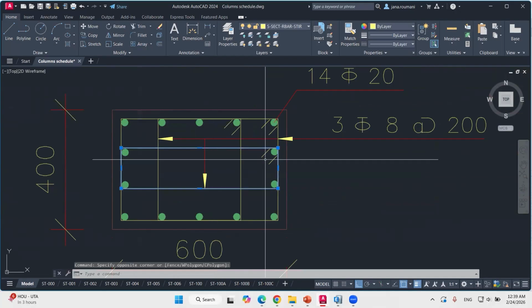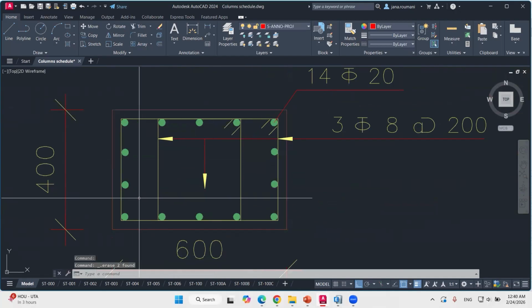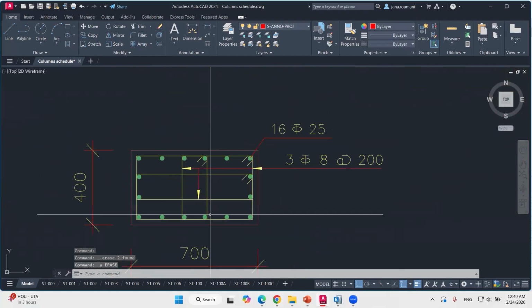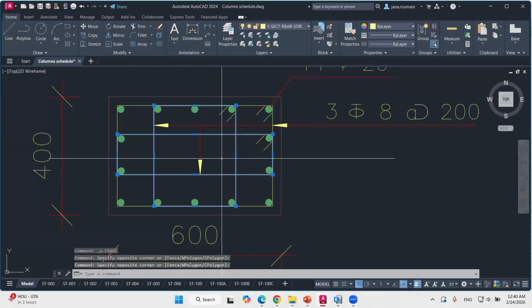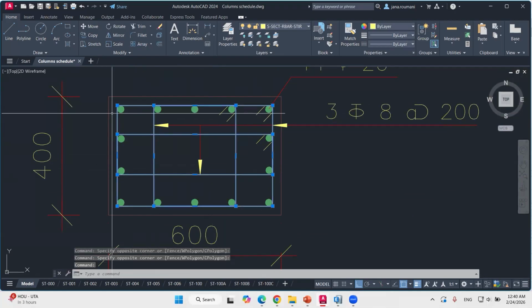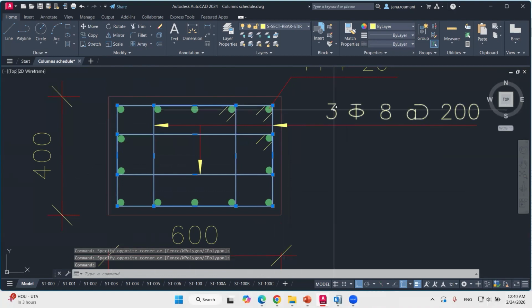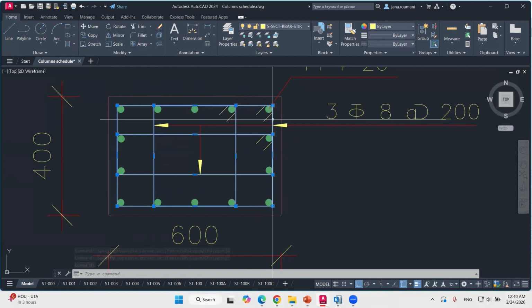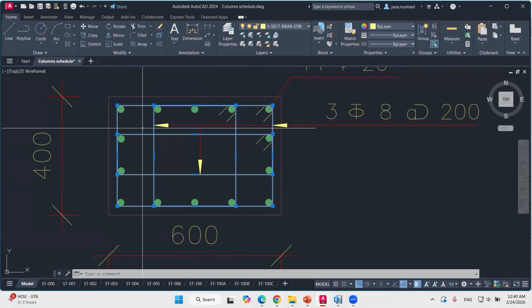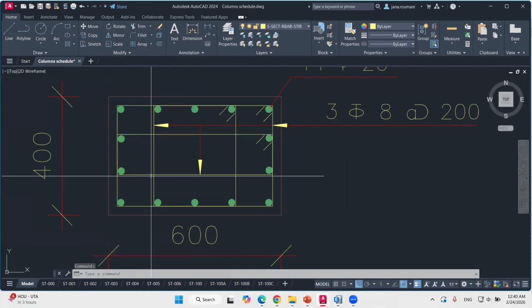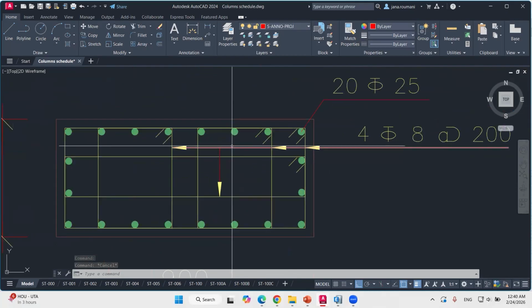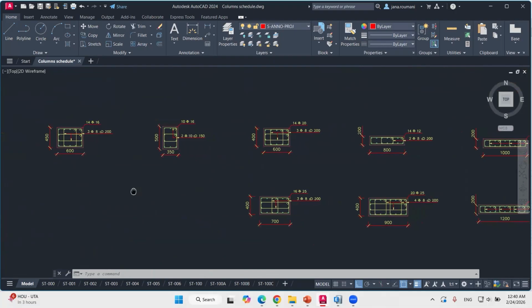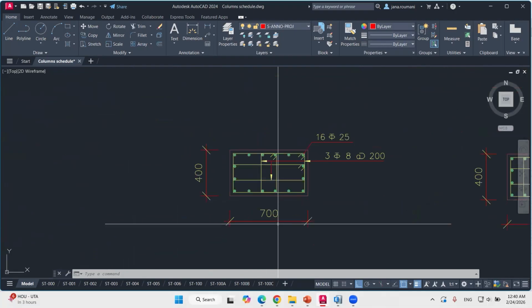Here, since we have 4 bars, we need to also provide confinement in the other direction. And of course, we have 1 stirrup, 2 stirrups, and 3 stirrups because we have an external one. So as if we have 4 legs in this direction and 2 legs additional in this direction. Same one here, and it's all in the same concept.